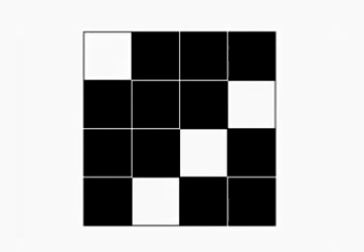This graph represents a 3x1 right-hand twill. As in the 2x1 twill, find the first warp yarn and follow the path of this warp yarn. There are 3 warp risers followed by 1 warp sinker per repeat. Follow the second warp yarn and you will see that the warp sinker is first, followed by 3 warp risers.